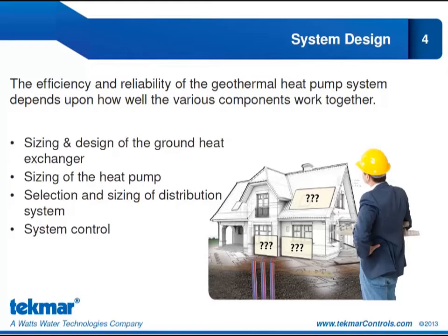Next, we'll look at the selection and sizing of the distribution system. It's not just the selection of the terminal units, it's how they need to be sized in order to work well with the low supply water temperature. And the last piece of the puzzle is, of course, where our expertise comes in, and that is the system control. And when I talk about control, I'm also going to be steering you towards zone control as well. So not just the system control, but also the zone controls and how those two can work together in order to optimize the geothermal system.